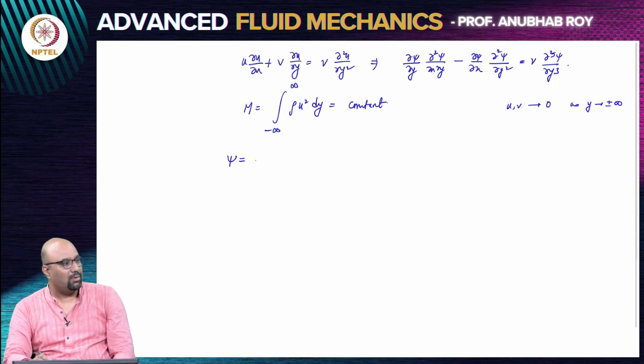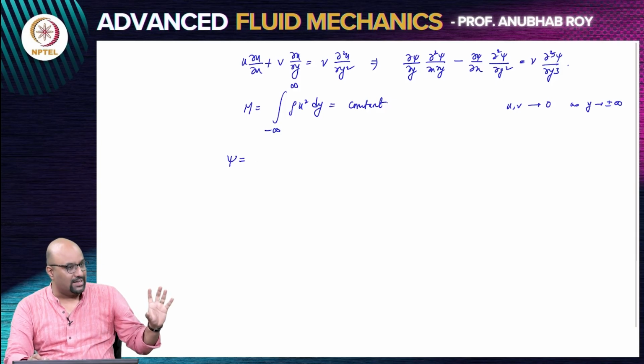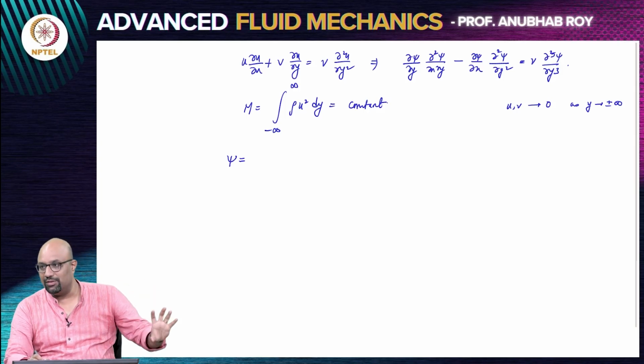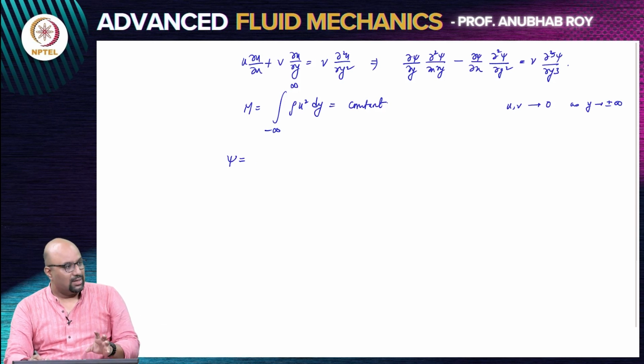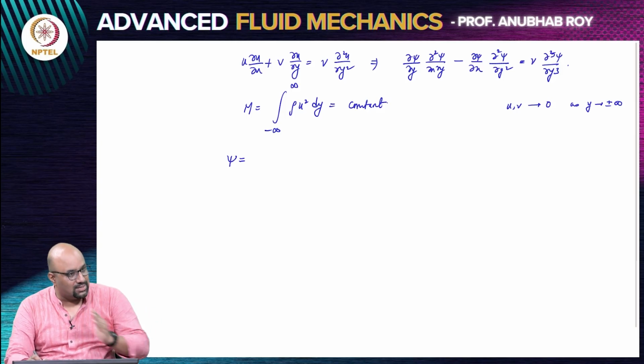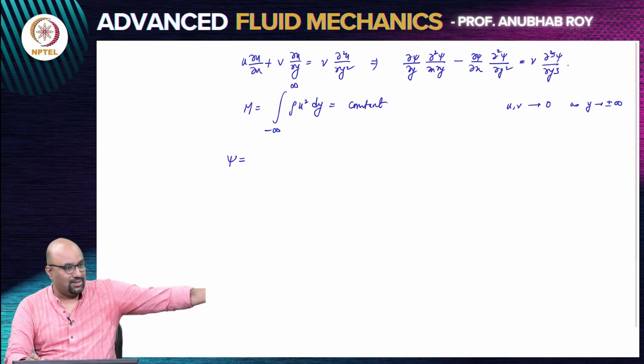In the Blasius problem, there was a uniform stream that was incident, and then you applied the boundary condition and you tried to find out what was the evolution of the Blasius variable. Now, here the problem is that at x equals 0, you have given some momentum flux, and that momentum flux should remain conserved for all values of x. That is the part which is conserved here, right?